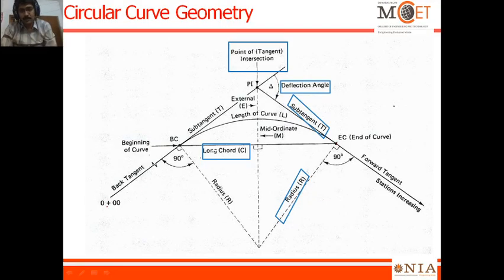Here it is 0 plus 0, 0 meaning the chainage of the starting point. It may be 100 plus some chains, some links, whatever they may give. So generally in surveying they denote the starting point by the number of chains plus links, or the total distance plus links. That is the notation they adopted.